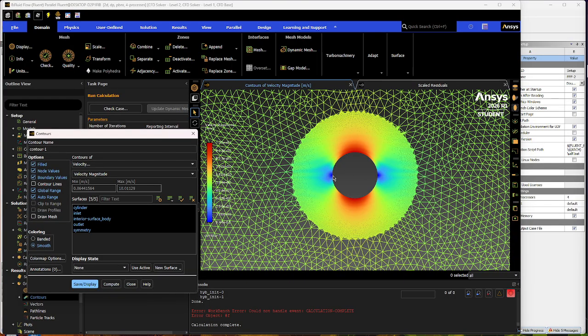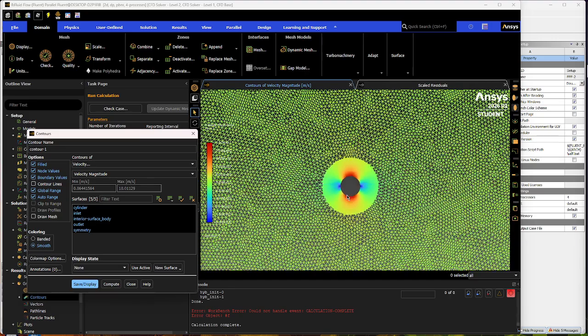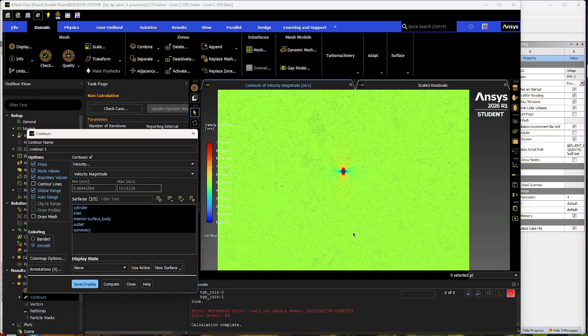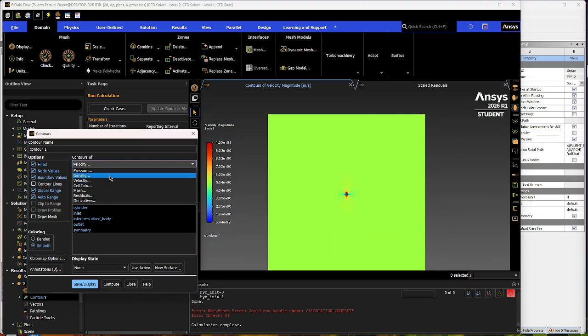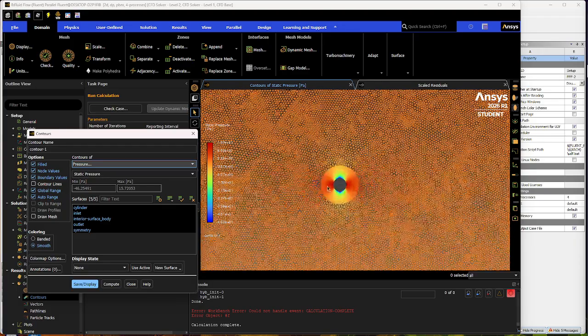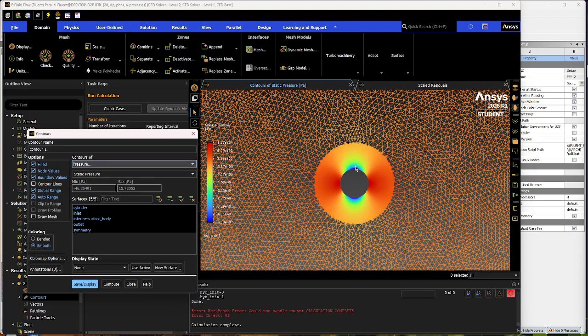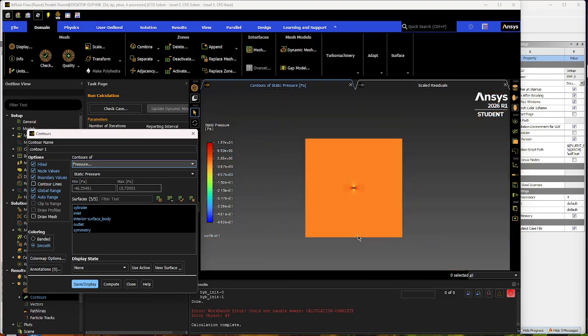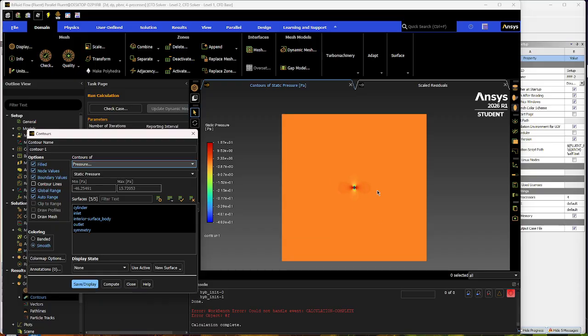So you have 2 stagnation points as dictated by the theory that we know we're supposed to get, and almost 2 times our U infinity free stream velocity there. So that is good. And then showing your pressure contour should be, yep. So max pressure at the stagnation points, the lowest pressure at the maximum velocity. That is all within expectations. So that's good.